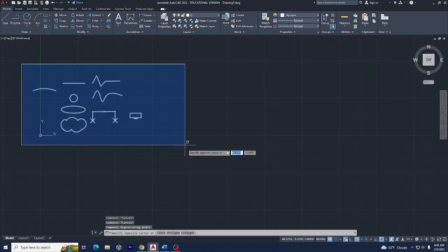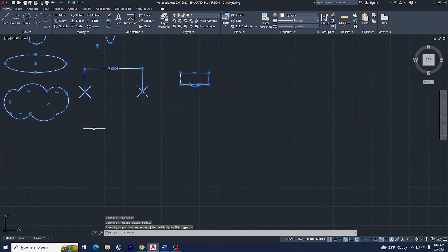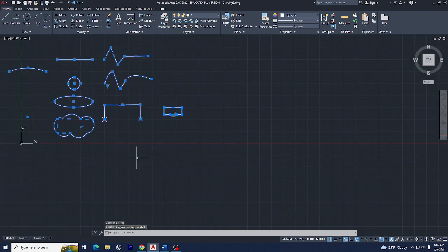As you can see, if I select all this, all their grips are now selected. Well, first you have to create objects to edit, and then you can edit them with the grips. Then you select objects like I've done here to make all the grips cold. You can see every grip is blue, so every grip is cold. Select the desired hot grip, so say I want to move this. Now I have that grip selected.